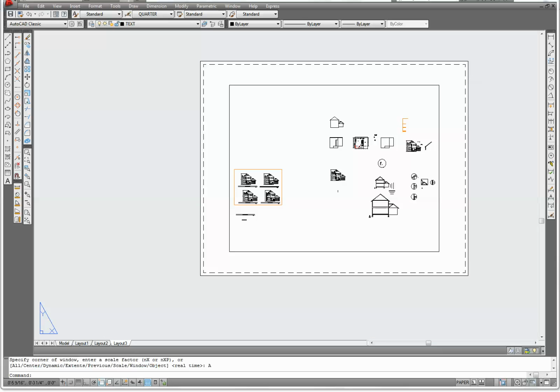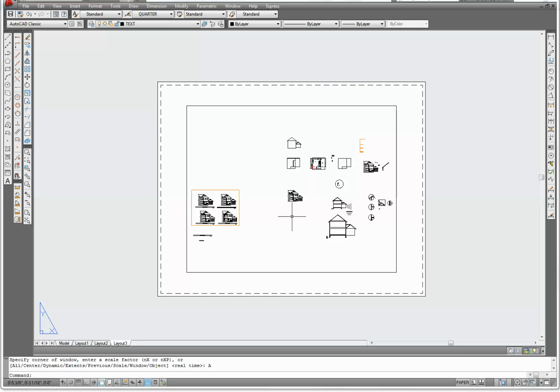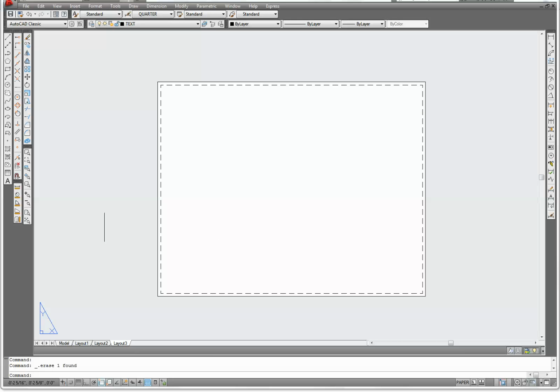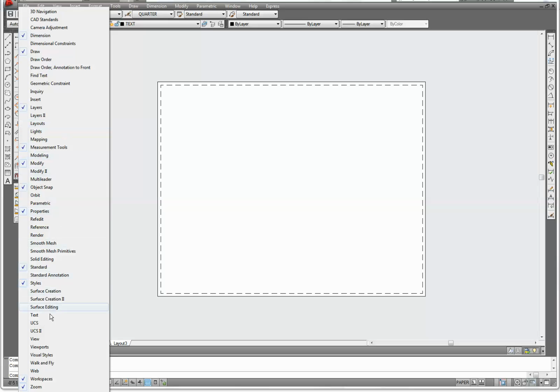This is a piece of paper in the screen. You may see something completely different inside this space here. Don't worry about that for now. Find this viewport line, rectangle, and click on it. And when the corners have these blue grip boxes on it, that's when it's selected. Then delete it.